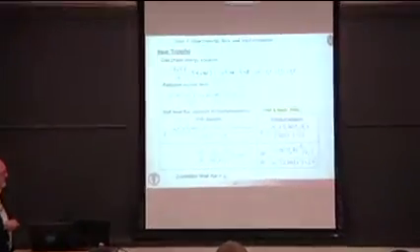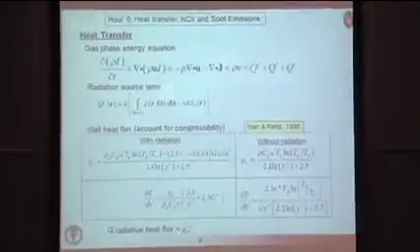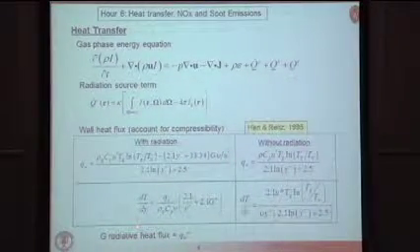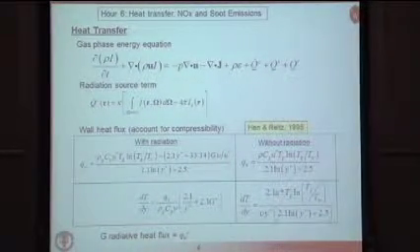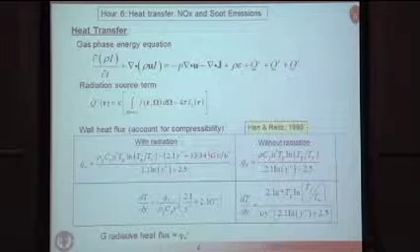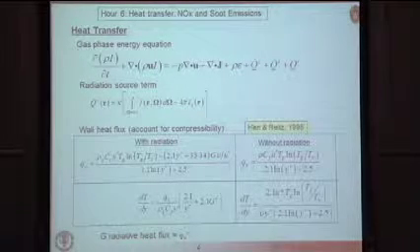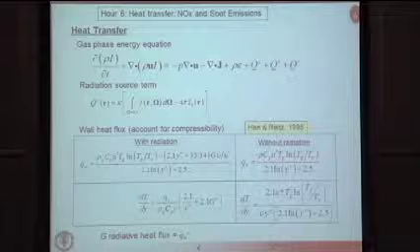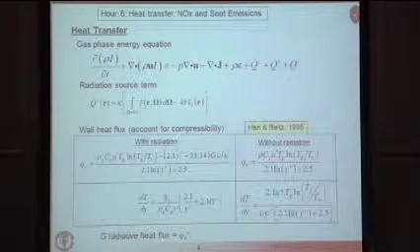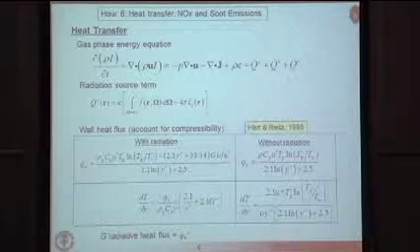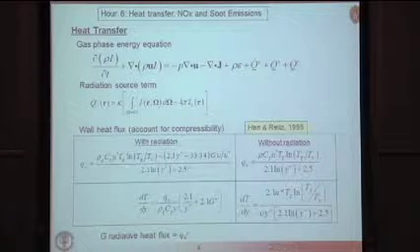And this term G is essentially the radiative heat flux, or it could be, if you have combustion occurring in the wall boundary layers, you could have a contribution to the wall heat flux as well. But here we're talking about radiation. So G would be the radiation heat flux, or radiative heat flux.